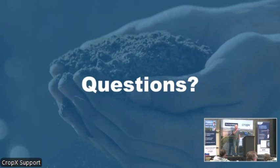One of the questions was compaction rates with water droplet size and everything else. Honestly, that only takes place two times. One, if you're pre-irrigating, right? Bare soil irrigation or post-irrigation. If we're irrigating bare soil, then yes, we definitely need to consider droplet size, all that kind of stuff. And there's all sorts of options out there about how we manage that part. But some other things that will help with that, cover crops, right? If we can get any plant interception to take the energy away from that water droplet, but it still goes where it needs to, that's a lot of things that will help out.